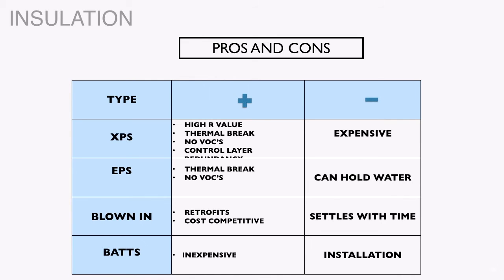Same with EPS, although one of the cons of EPS is that it can hold water. It does create thermal breaks. There are no VOCs with either of these rigid foam board products, so that can be important again in these sort of specialty cases.